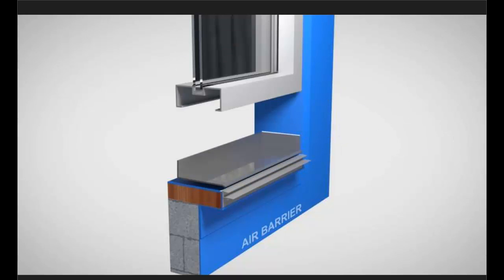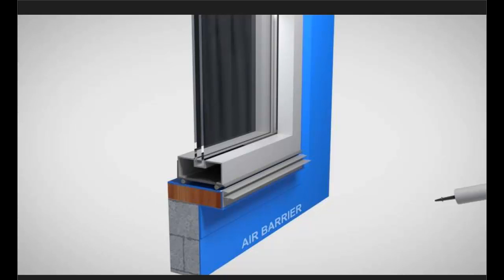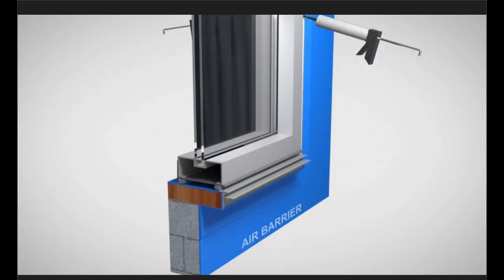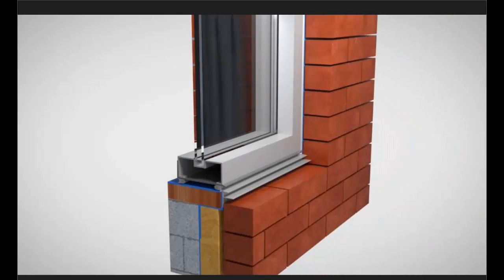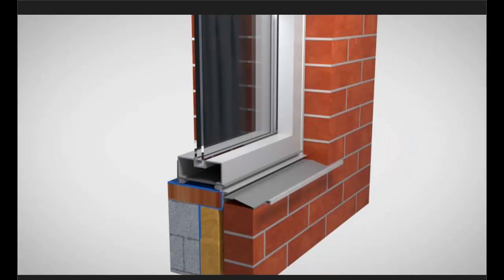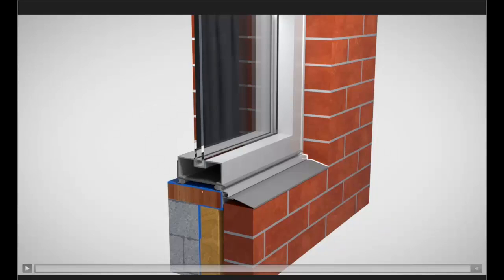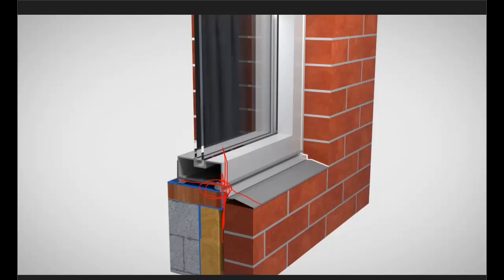That's the clip. Your sub-sill would be part of your storefront assembly. There's no flashing attached, nothing hanging out, nothing that's going to get damaged yet. Lastly, they come back and clip the flashing in place. So now, rather than attaching your flashing by shoving it under the window and giving it a horizontal attachment, we're attaching it on the vertical face of the wall. And we're allowing the perimeter seal between our storefront and the air barrier to actually come together rather than interrupting it with flashing.